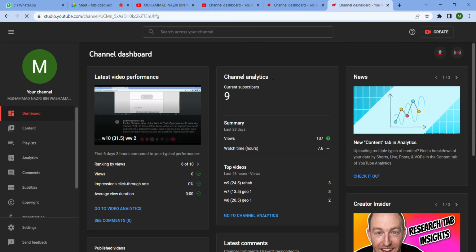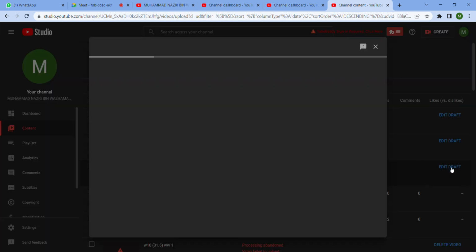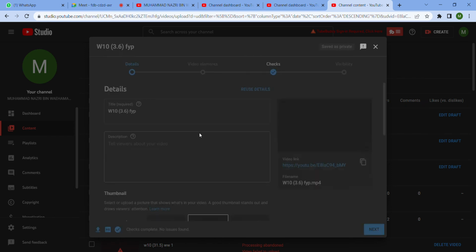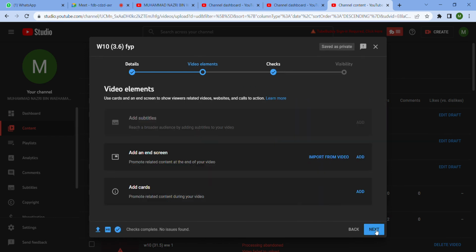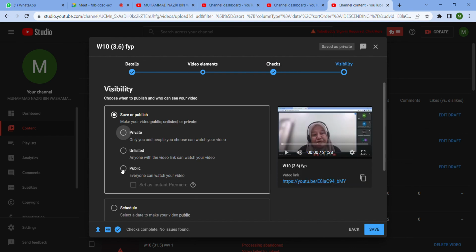MBR, because no clarifiers are needed and no pre-treatment, no tertiary treatment are needed, because you already use the MBR. So remember, why do I say no pre-treatment is required? Because, sorry, I keep mentioning moving bed bioreactor. For a membrane bioreactor, normally we use ultrafiltration and microfiltration only.